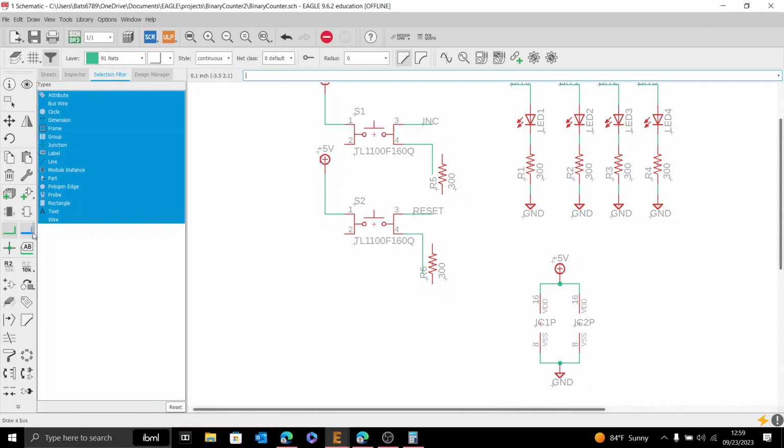So before I get too far, do you guys understand the idea of a pull down resistor? Does anyone not know what a pull down resistor is? Okay, so I'll explain this real quick. The idea is that if we don't pull this down, then this value could technically be in the microvolts, millivolts, who knows what. With a pull-down resistor, you are giving it a fixed value. This is ground. And we make it a resistor, so that way current, when we do want to change it, will hopefully flow to whatever we want to control, because there'll be less resistance there.